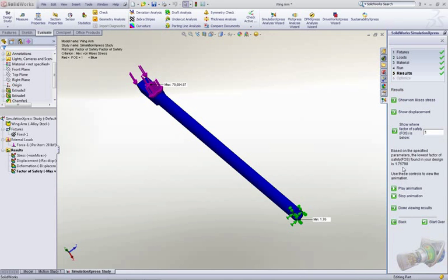When loads are applied to a body, the body tries to absorb its effects by developing internal forces. However, these internal forces vary from one point to another. In Simulation Express, you view a stress quantity called the equivalent stress, or von Mises stress. An equivalent stress value does not give you the forces on the part at every point. It gives you a number which reveals the overall safety of the design.